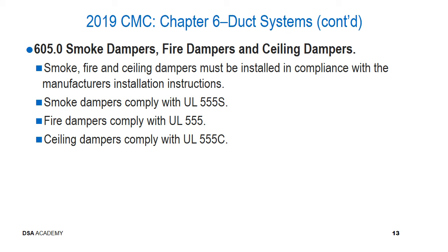And it's also, of course, very important to verify that the damper blades are installed within the plane of the rated wall. A lot of these things, or most of these things and more, have or will be identified and discussed in the fire life safety portion of the Product Inspector Overview class.